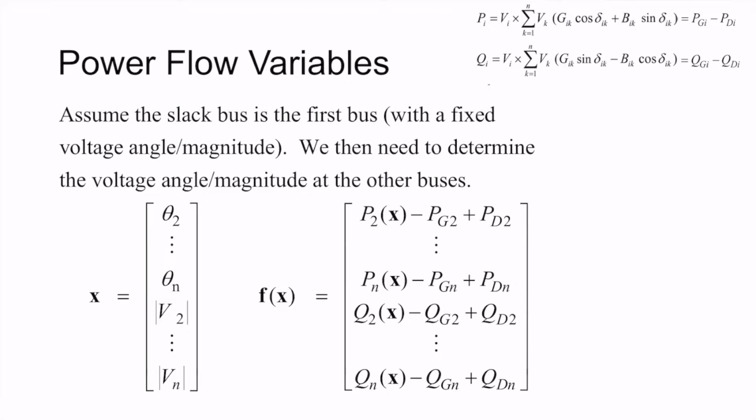Then my decision variables for this load flow or power flow will be the voltages from node 2 up to node n, both angles and magnitudes. Remember that those phasor voltages represent the state of the system. Knowing this, finding this solution will be enough for defining any power or any current in the system.